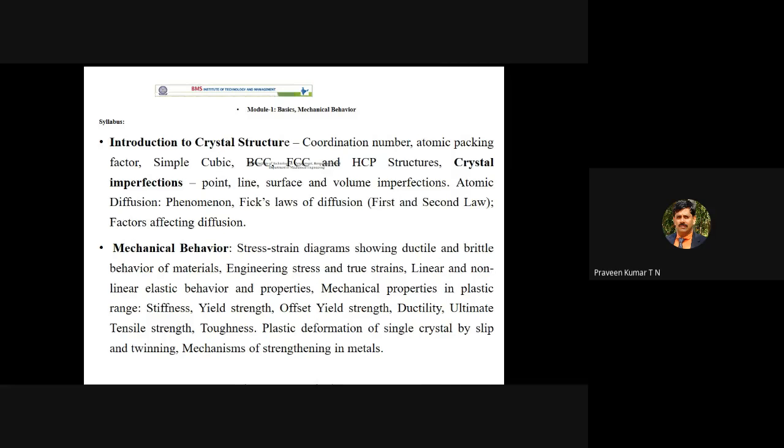There is no recovery. The material undergoes deformation. Once the load exceeds the yield strength of the material, it will undergo plastic deformation. How plastic deformation takes place at the macroscopic level, you are studying this: your elastic limit, plastic limit, and your linear and non-linear behavior.